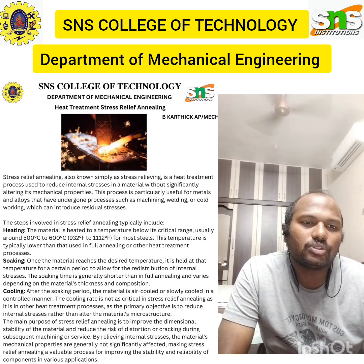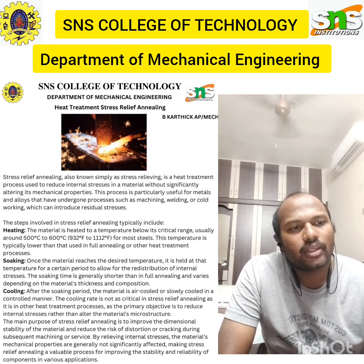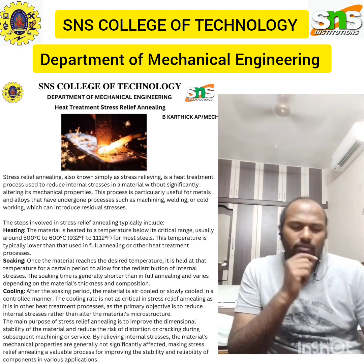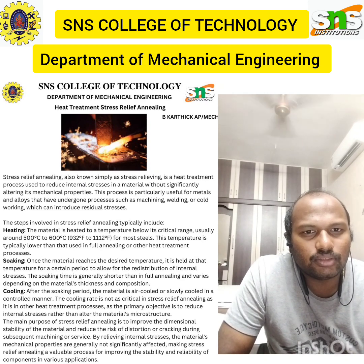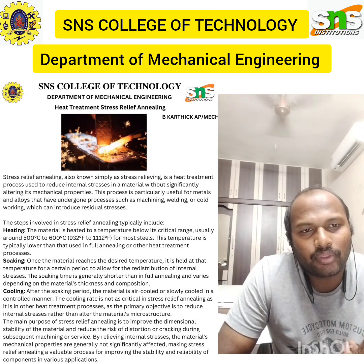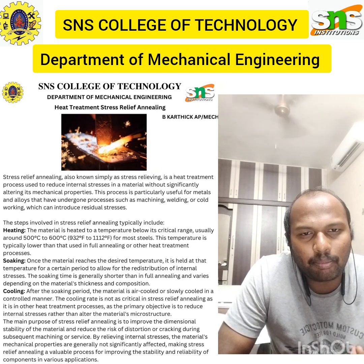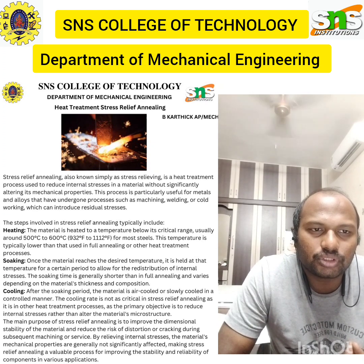into the material. Stress relief annealing is commonly used in industries where dimensional stability and stress control are crucial. When we speak about dimensional stability, for example, if the material used for the landing gear of airplanes is not stress relieved, meaning it is not dimensionally stable, we can't land the airplanes safely. So there comes the dimensional stability, and stress control is very crucial.